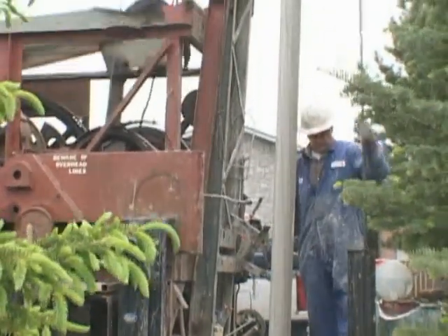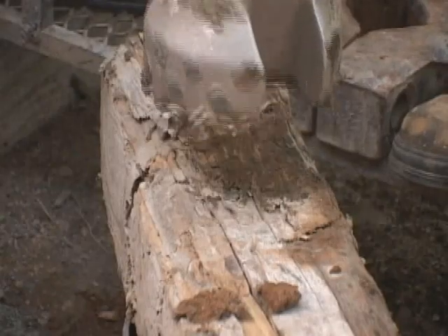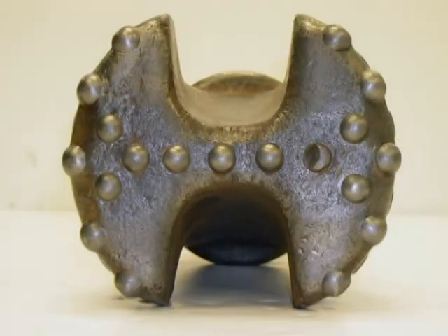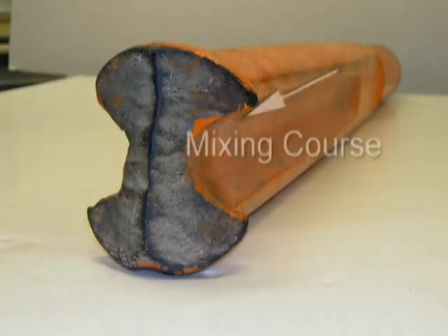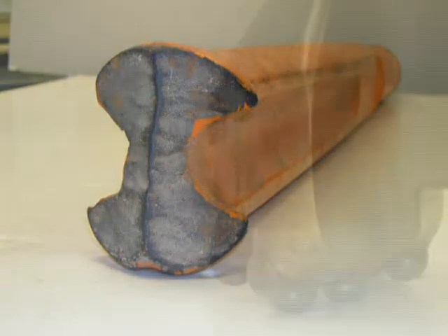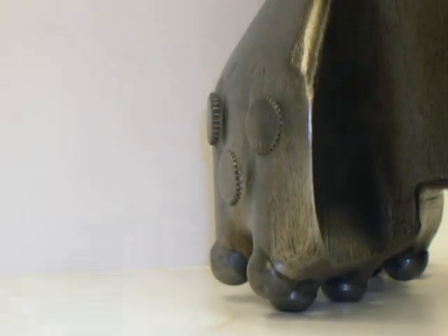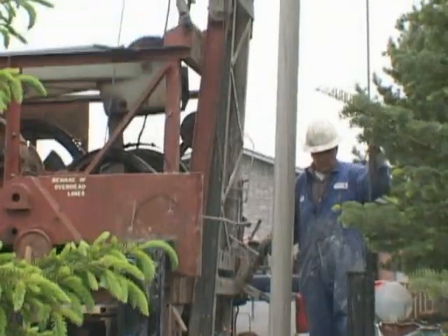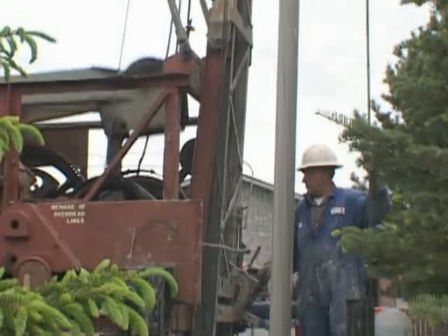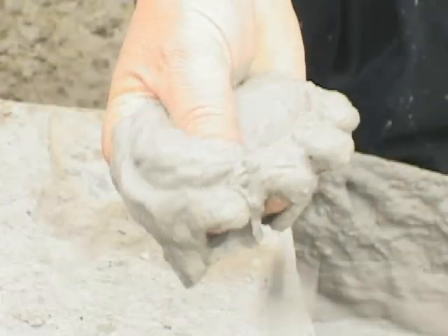These functions include penetrating the formation beneath the bit, crushing the formation into small fragments, mixing these cuttings with the introduced water present in the borehole, and finally, reaming and maintaining the hole diameter in rock formations. The lifting and dropping sequence is performed once every second until such time as approximately 3 to 5 feet of material has been drilled, resulting in the introduced water being totally saturated with cuttings.